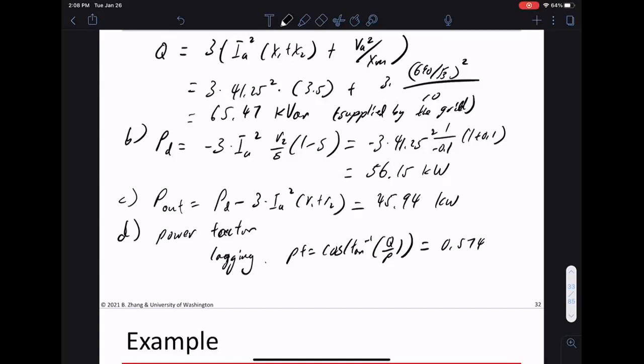You tried very hard to get this reactive power from somewhere else. So you have variable capacitors, you have STATCOMs, you have different setups, all of which are used to provide this reactive power. So this is something to keep in mind. This generator does provide active power fine, but does not provide reactive power.